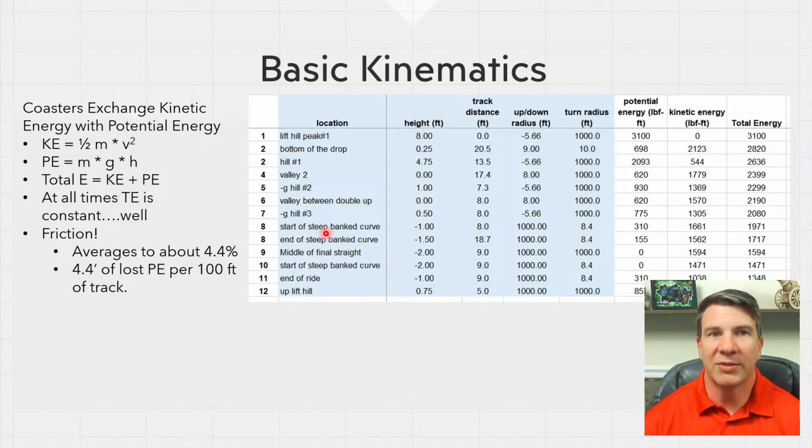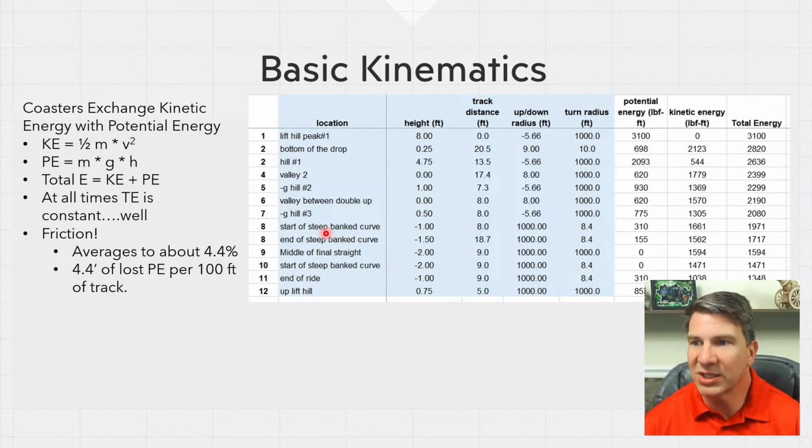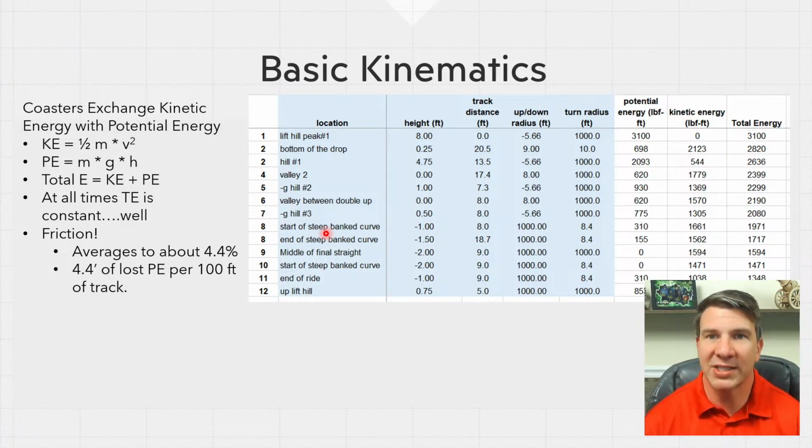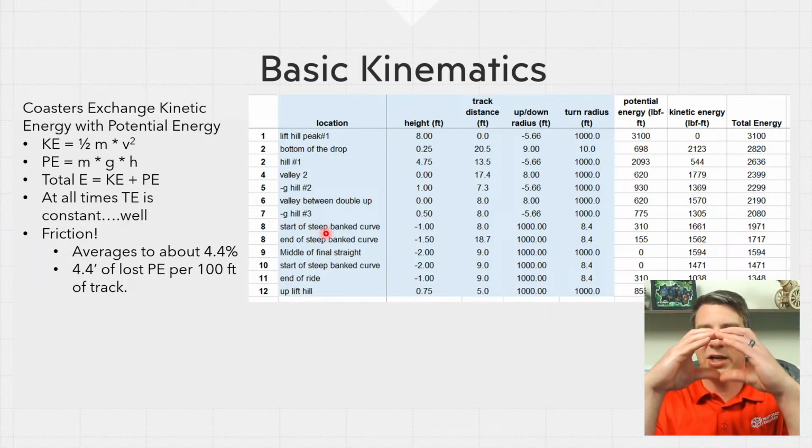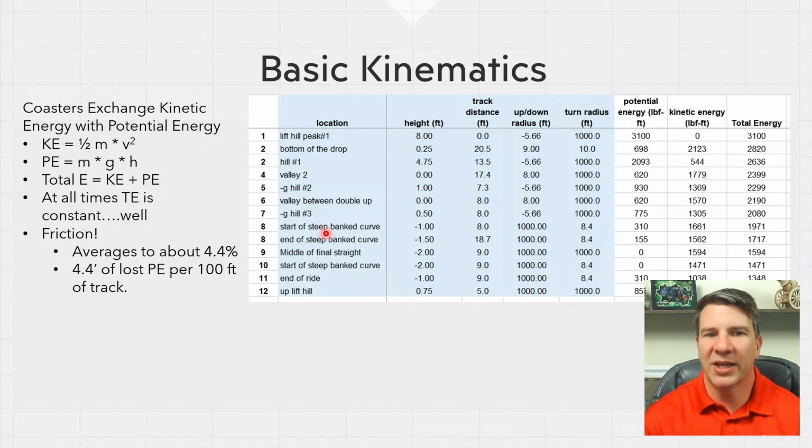Also, the track tires, since they're plastic, will deform. That's where a lot of energy comes up. And the track itself will deform, whether it's the whole structure or even just the tubes of the track squishing down. That is energy that is put into the steel and released that is not given back into the system in the form of speed or energy. It's just dissipated.